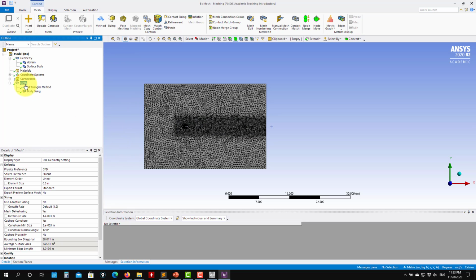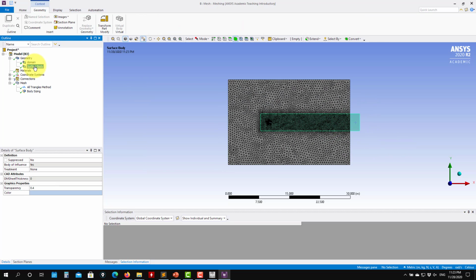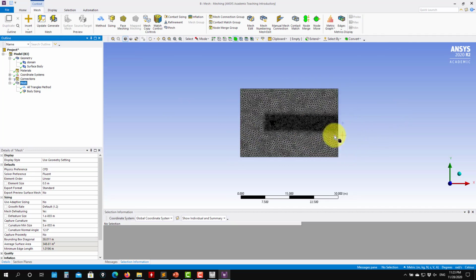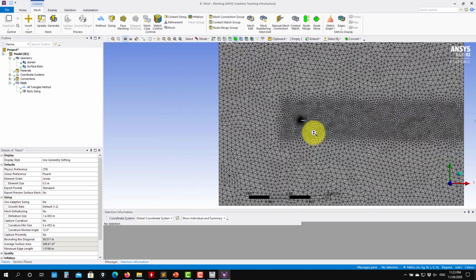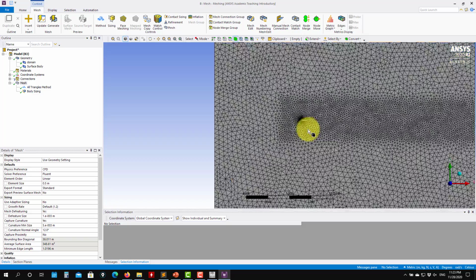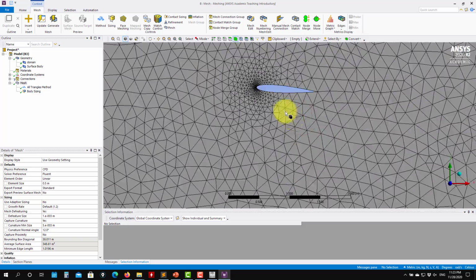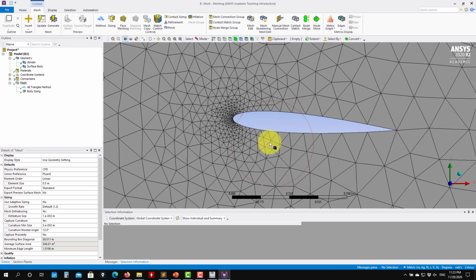you have this. Now you don't see the surface, it's being used just to add that refinement. And we're getting there. So now you get an idea. There are boundaries here, you need to give values, you create your refinement, but now we can also add refinement in the surface. So remember, in the airfoil you have a boundary layer.